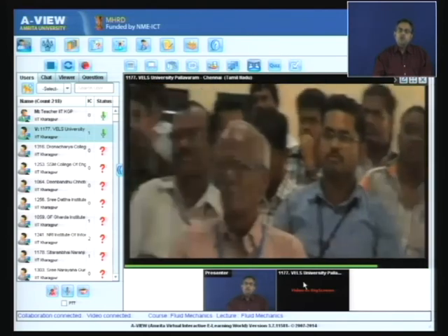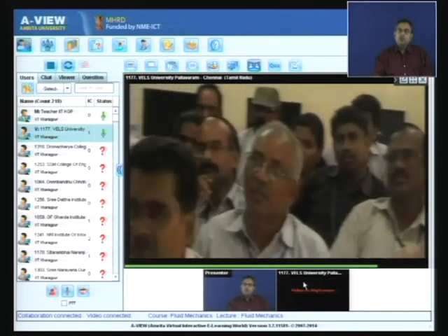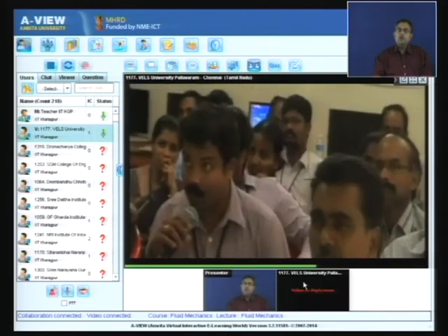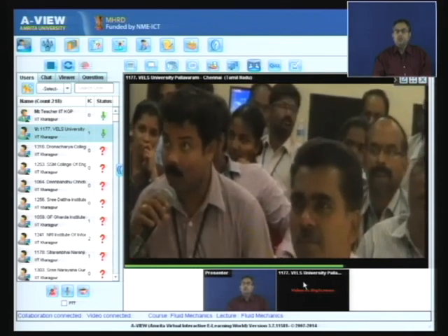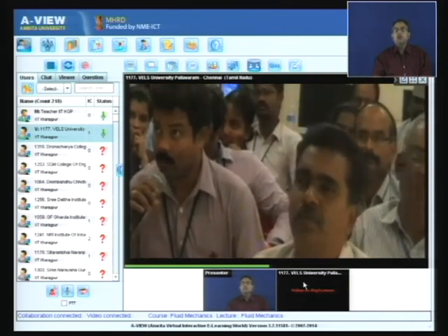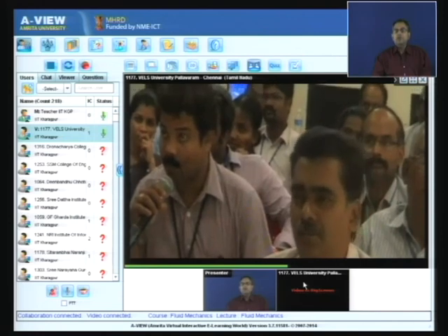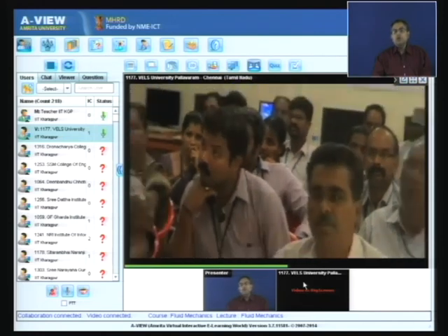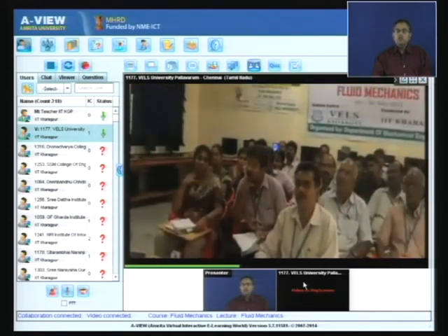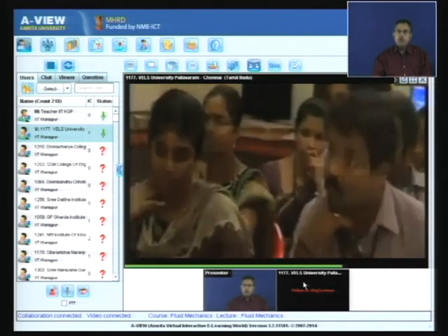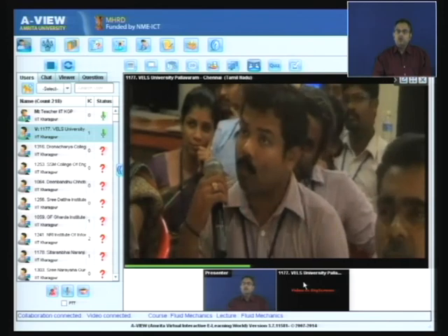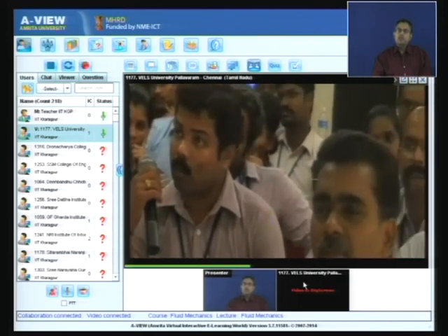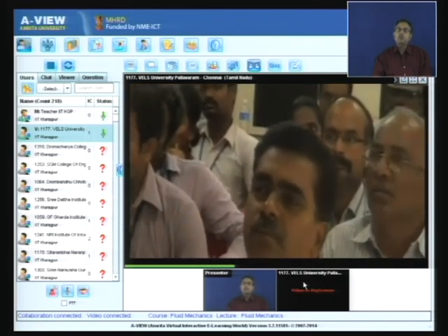Combined Poiseuille and Couette flow. There also, at y equal to 0, u equal to 0, and at y equal to h, u is equal to u1. That boundary condition does not change irrespective of whether it is pure Couette or combined Couette-Poiseuille flow, because that depends on whether there is a pressure gradient or not, but the effect of a pressure gradient does not affect the boundary condition at the bottom plate and the top plate.